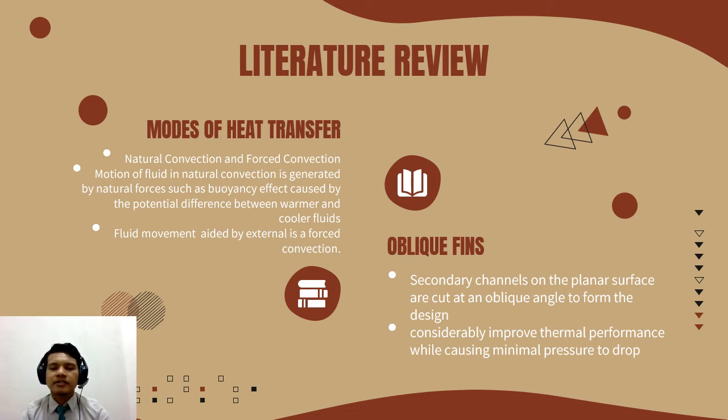In oblique fins, in the context of my project, oblique fins are secondary channels on the planar surface that are cut at an oblique angle to form the design of a heat sink. It considerably improves thermal performance while causing minimal pressure drop.